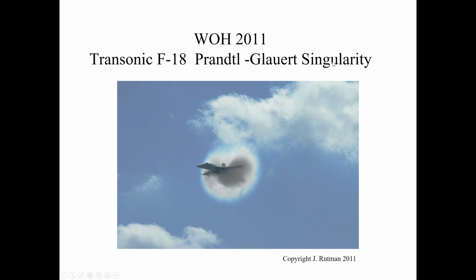Technically, it's the Prandtl-Glauert singularity. The plane is not breaking the sound barrier. Basically, it's flying so fast, it's compressing the water vapor into a vapor cloud. The shape of the singularity strictly depends on the airframe design. Different airplanes give different condensation patterns. Basically, it looks like it's flying out of a hole in space. It's pretty neat how it works. But anytime you're transonic on a humid day, you'll see that vapor cloud, that shock wave being formed, depending on the perspective, at either the front or the rear of the aircraft.